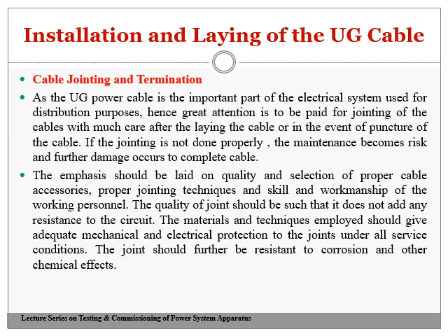it will start operating properly, where we get a supply, and the generating station or a substation provides the proper supply to the utilities, or the consumer as such. After the aging of the cable, there may be some sort of breakdown in case of the underground cable. At the time, it is essential to find the fault as well as remove the fault, and afterward the jointing can be done as such.